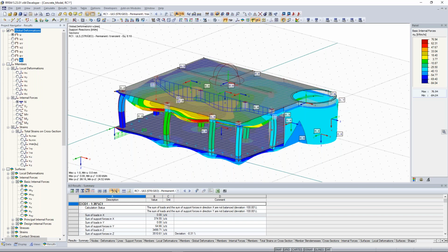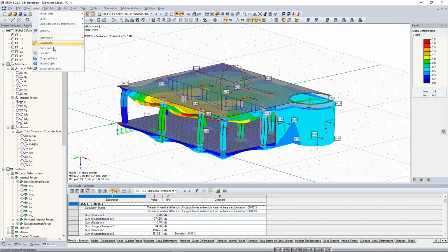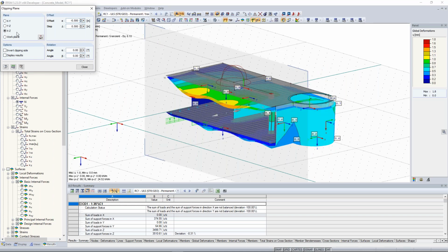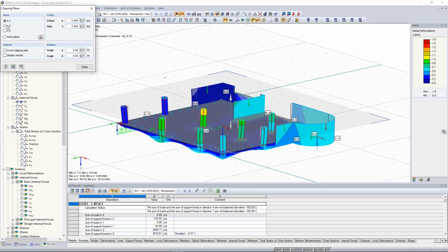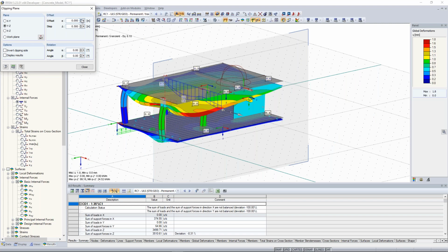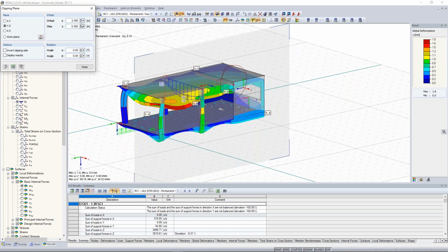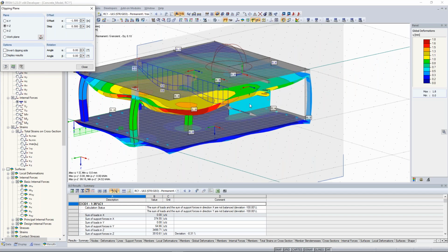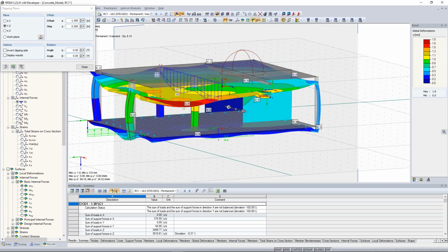first of all the clipping tool, you can cut the plane, set a step of 0.5, for example, and then you can choose this offset, also choose the right plane, and so on. And then you see every time the different values there. It's very helpful.